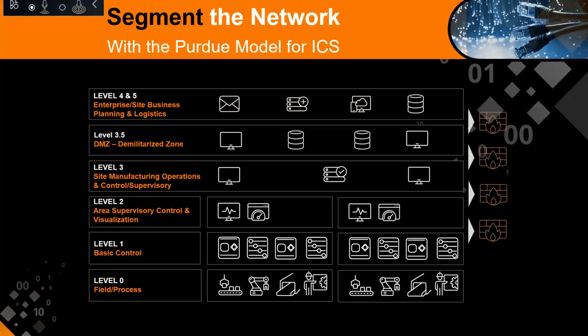And when looking at today's industrial networks, I sometimes see that the OT domain, so to say, is a single VLAN or sometimes 2 or 3 VLANs on the IT network. So the industrial network is sharing hardware, sharing switches with the IT domain. And in itself, this may work, especially in smaller environments or in environments where there's no budget for separate hardware.